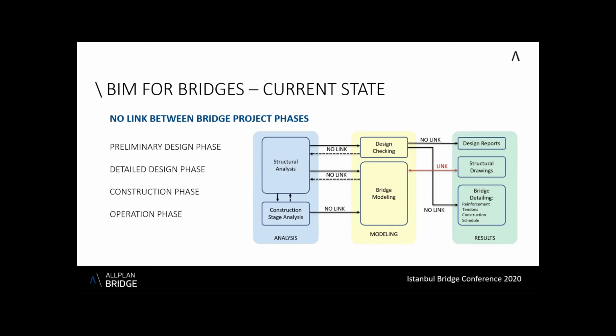BIM is generally conceived as an overall strategy for coordinating all required works arising during the design, construction, and operating phases of structural objects. This goal is achieved by using an integrated digital model of the structure and procedures directly communicating with it in all task settings throughout planning, construction, and lifetime. The aim is to ease and accelerate the processing by avoiding errors due to multiple and redundant data entry, as well as to improve the overall quality.